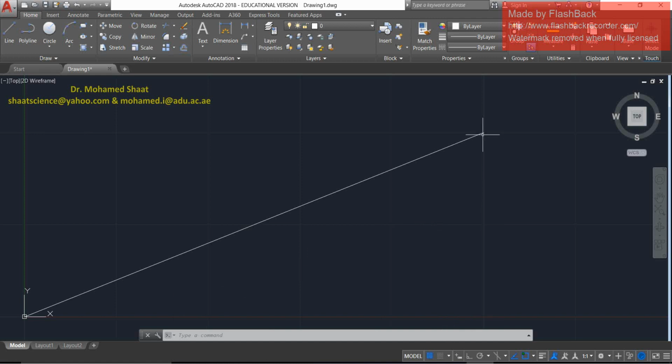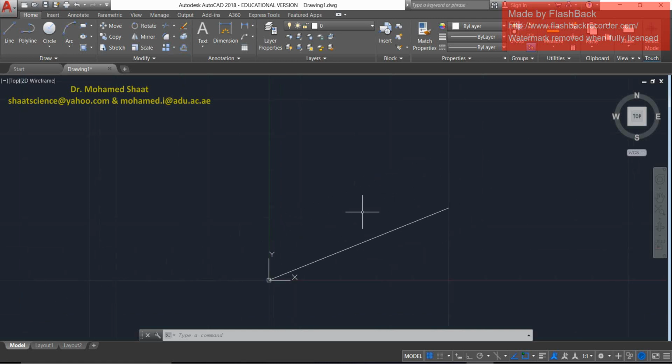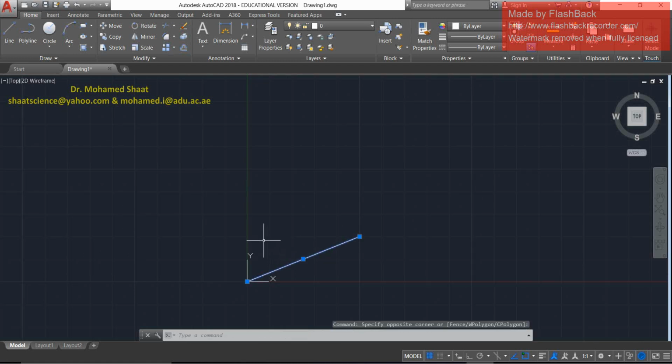So this is another way which is more accurate, but it is not more practical. It would take time, because it is not practical when you have an engineering drawing with so many details to break it down into points. But this is one of the options: you can use the keyboard by specifying the coordinates of the 2 points to set up a line and so on. We discussed this one, again as a kind of revision.